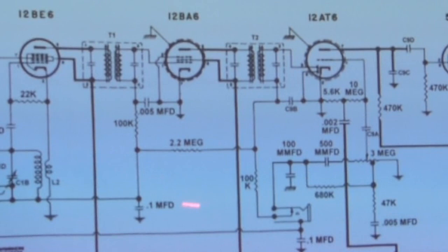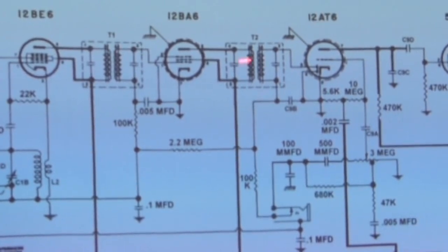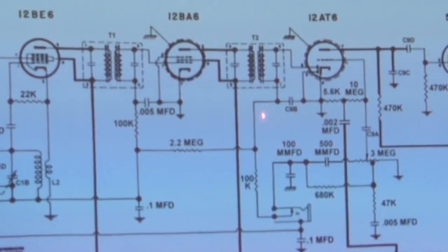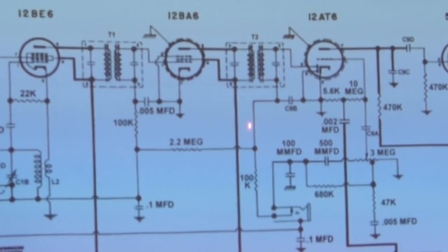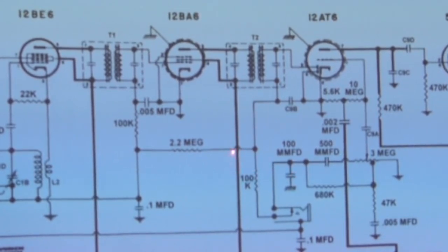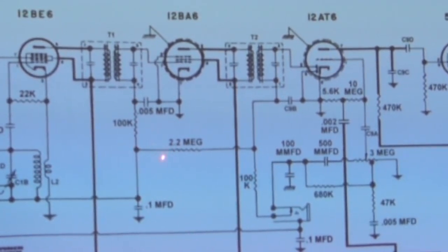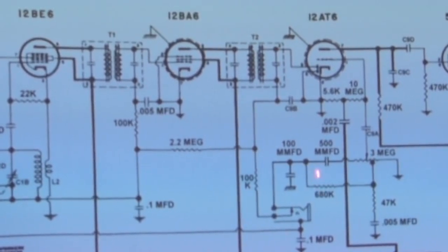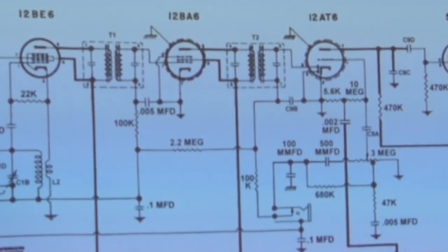Now, Rick and I were working on a radio, and we found out that we were getting an audio signal down through this line here, but it was distorted. It was garbled, and you were getting... What could be wrong? In this part of the circuit, what could be wrong? Capacitor? Coupling capacitor? Yeah, okay.